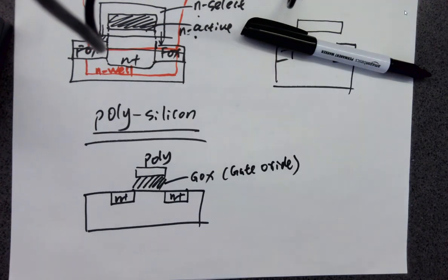Okay, and this is another thing you need to know, starting from lab 3, I think, because a lot of times you are trying to connect the gate or have an extended length of gate wire, but you shouldn't use a long gate material, poly material, because it has a larger resistance compared to metals.